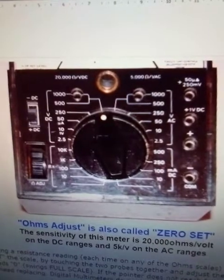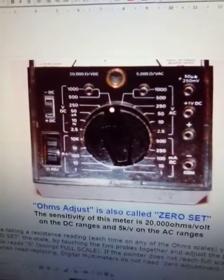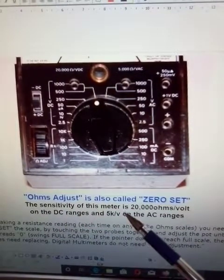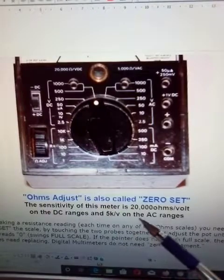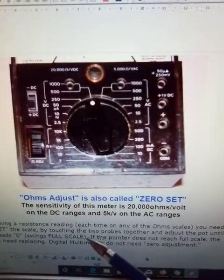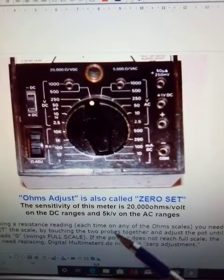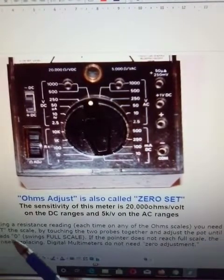Now all I'm doing here is bringing this close so you can see the readings on the panel itself. Okay, and this ohms adjust is also called zero set. The sensitivity of this meter is 20,000 ohms per volt on the DC range and 5 kV on the AC range. Before taking a resistance reading each time on any of the ohm scales, you need to zero set the scale by touching the two probes together and adjusting the pot until the needle reads 0.